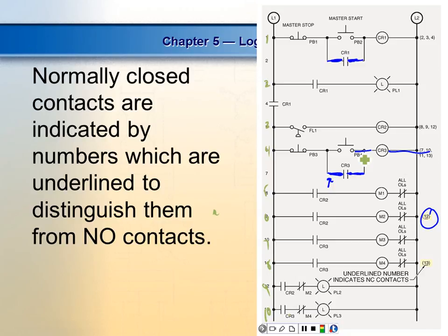You got in your mind to get a line number, it's got to go to L1. You got in your mind to get a line number, it's got to go to L2. So I could come over here and do this, and put another relay. I got to put a load in there, right? I have a short circuit. Well, I've added another line number, so I would follow this over and give it a number, right?